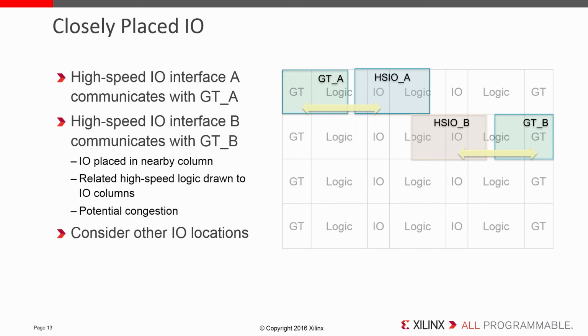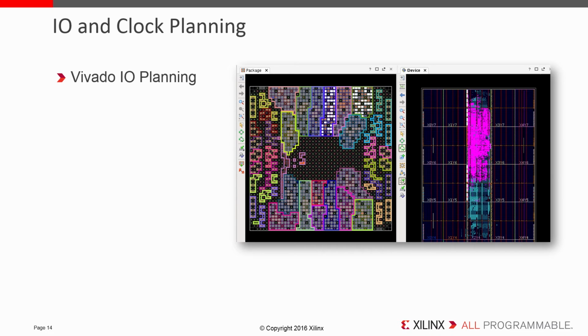I/O planning can uncover problems even more effectively when including the key pieces of the design, such as the high-speed I/O interfaces, or even mock-ups of key IP. Use the I/O planning flow in Vivado to explore the implications of I/O pin assignments.